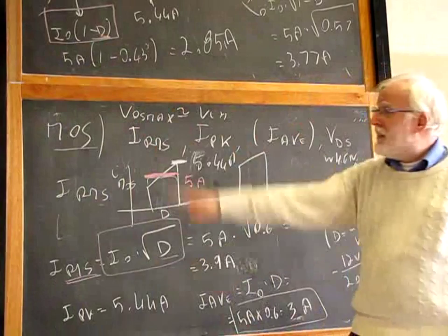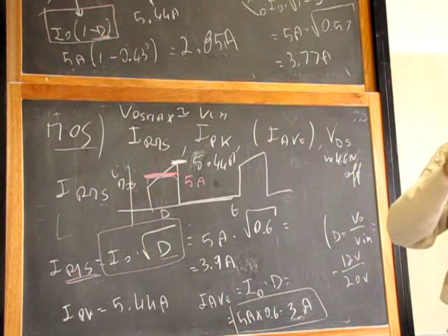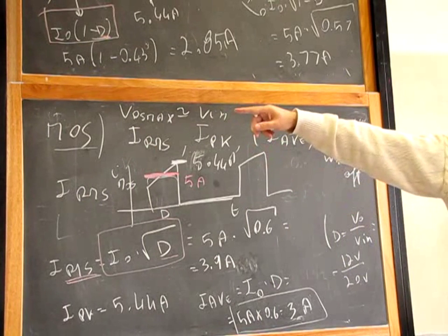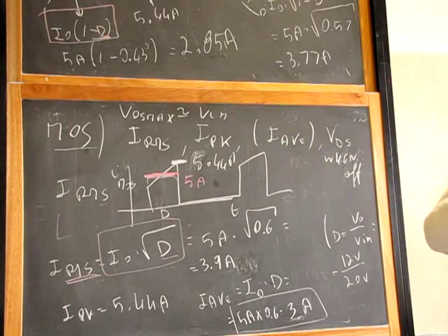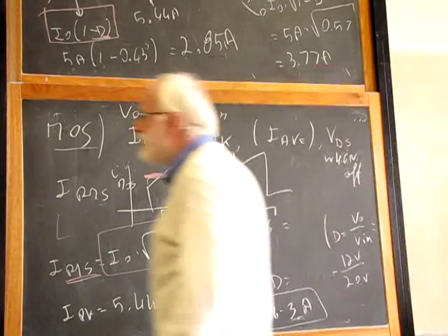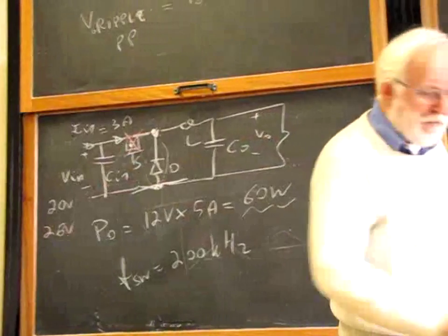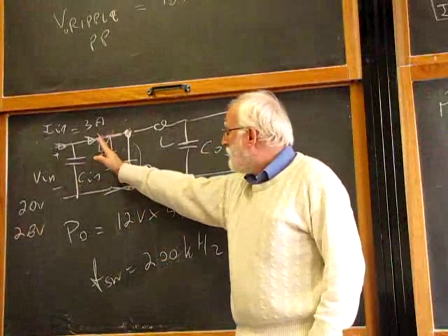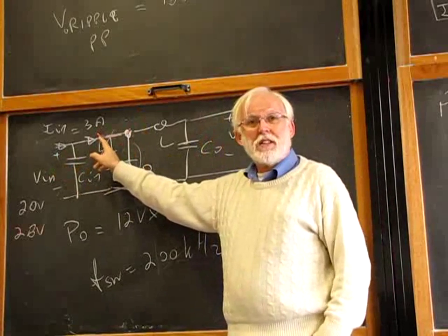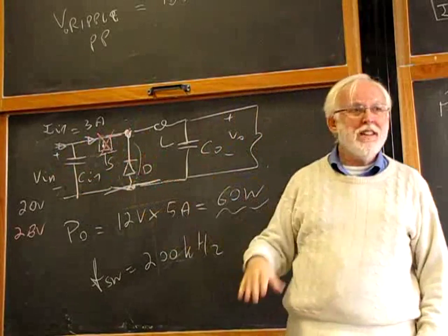Oh, by the way, if you are on your truck, you can have a voltage glitch that goes up to 50 volts. So if you pick a 40 volt MOS transistor and you have a 50 volt glitch, your transistor is not too happy. Put protections in front of it. This capacitor acts as a protection. It's not the best you can have, but better than nothing. But put your protection, because in a buck converter, MOS and diodes are on the front line. Anything that comes from the supply goes directly to the switch and to the diode. So if you have an over voltage over here, the two components are the first to fail. Diode and MOS.